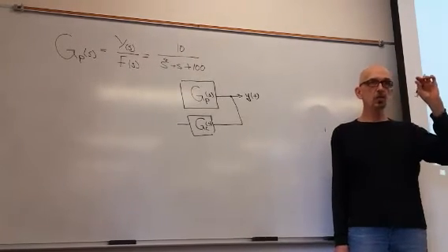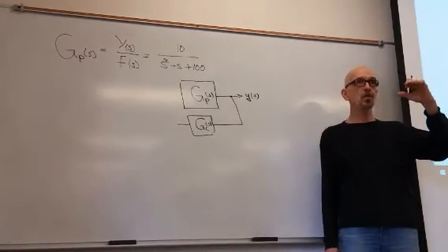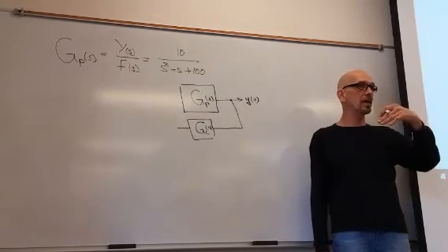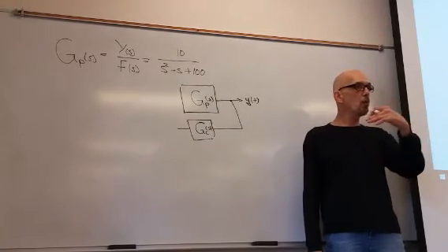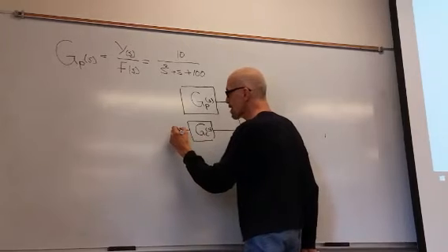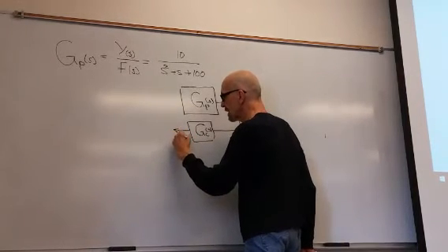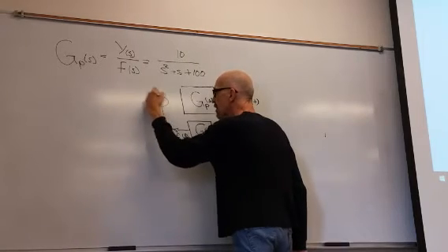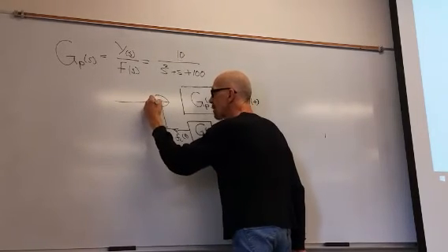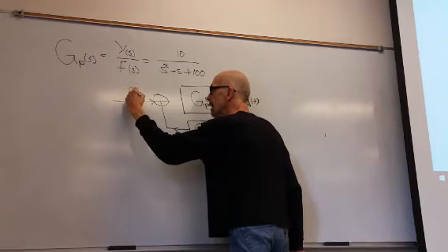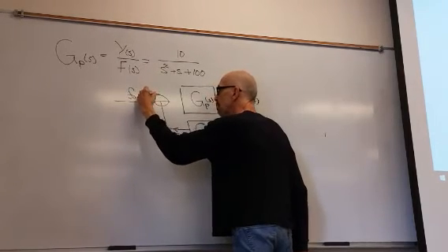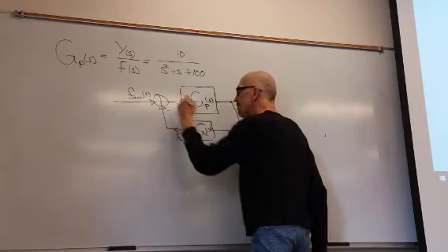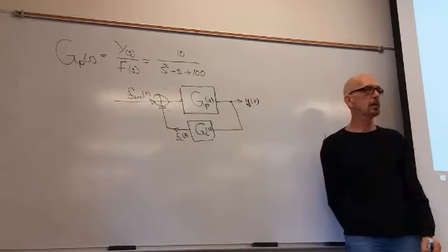It's measuring a displacement, but then it's computing a force, because that displacement relates to strain on the wing. And that force, the controller force Fc, is going to counter the aerodynamic forces that are exciting the wing. And it's that difference of forces that's going to be applied to it.